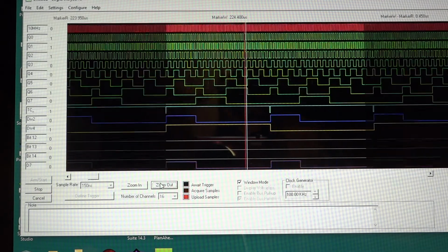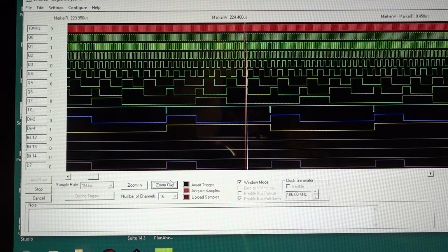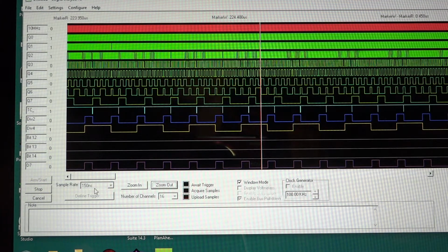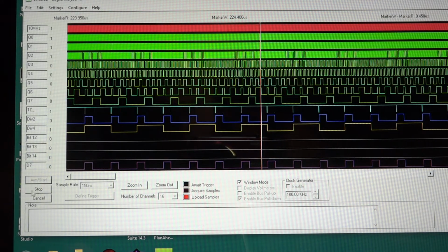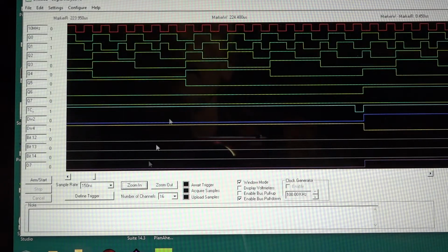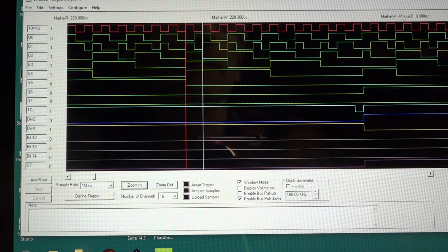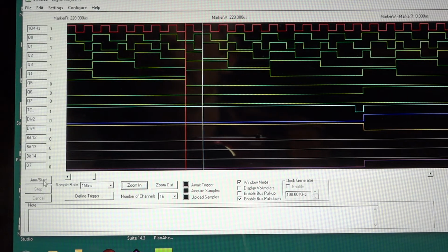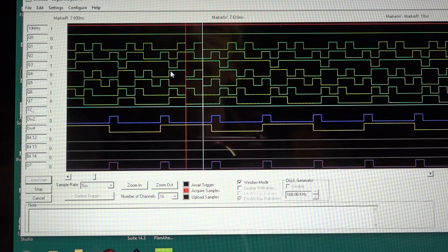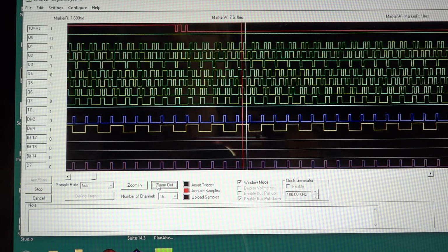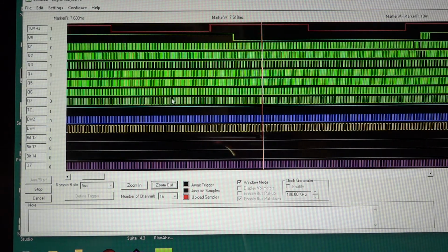If I zoom out more, of course now it's not going to show that, but you can see it there. If I can stop it, get one. If we zoom in on the clock, you can see it'll start lying, saying that the clock cycle is 300 nanoseconds, and we already know it's more like 100 nanoseconds. So this is called aliasing problems, where if you sample too slow, the data starts getting very goofy looking. I'll make that even more apparent if we go out to 5 microseconds. You can see the clock actually looks like it's vanishing or slowing down. And this is what happens when you sample too slow.